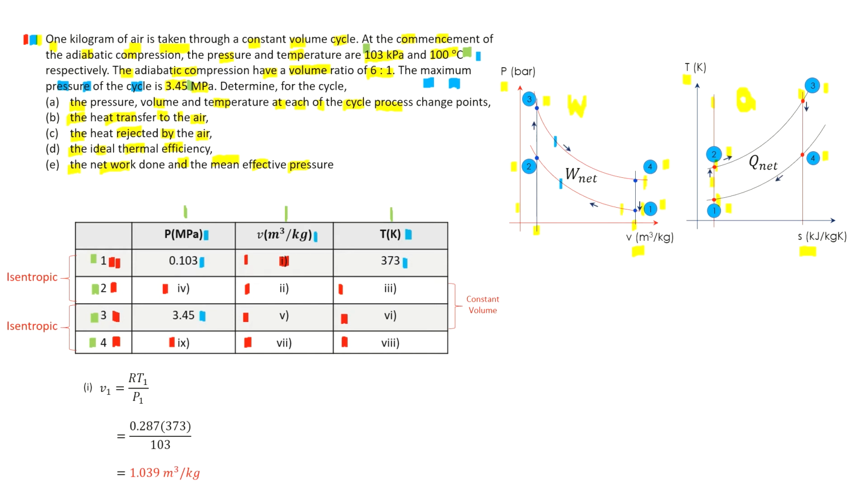Okay, for our example here, always when you are solving the problems, or if you are asked to find out pressure, volume and temperature of each state point, then it is better for you to get a table prepared like this and then look into the table, analyze and see what are the unknowns and what are the data you should obtain first.